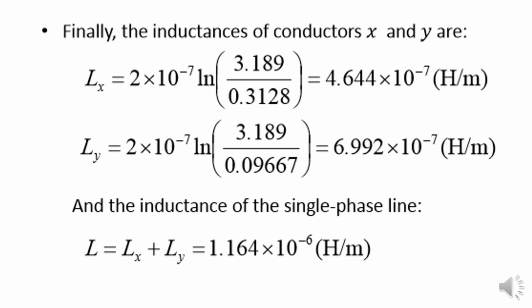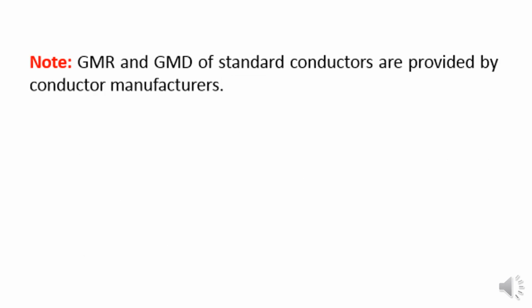We have manually calculated GMD and GMR values for x and y conductors by using the given equations. The proof of this Lx and Ly, we can do later. But there are standard conductors, so it is not like we can always calculate GMR and GMD values by ourselves.